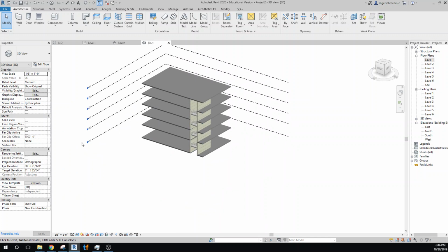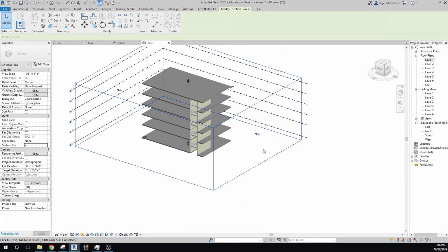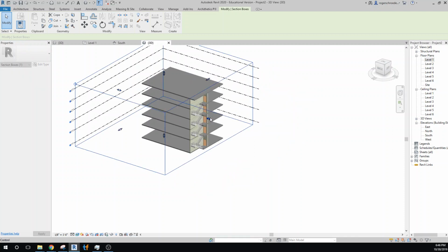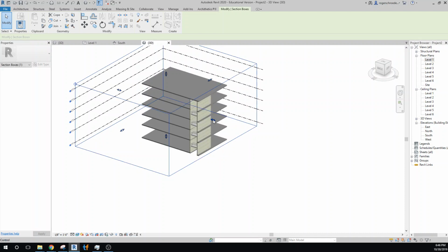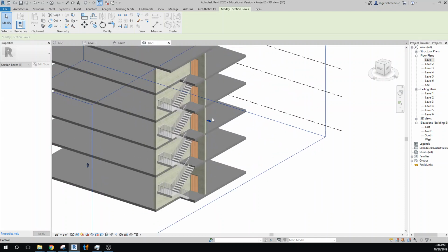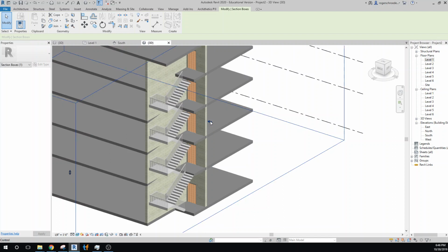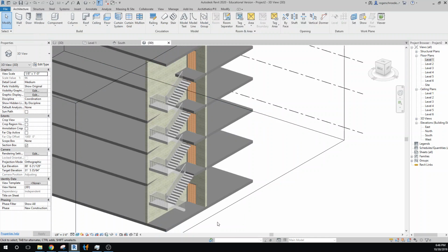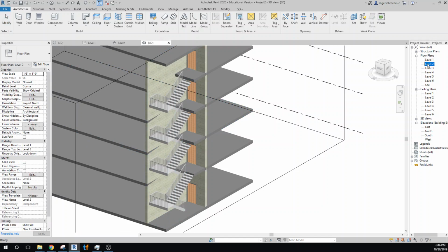And we'll think about ways of actually presenting this that make it a little more descriptive. Maybe pulling back a section box until we can show the whole construction of the stairwell. Need to zoom in there a little closer until we can get it just at the right position there. So, and we actually don't need the shaft wall going all the way down to the bottom. So you notice I can just pick this up again, and we've removed that shaft wall from that. And the other thing I'm a little bit unhappy about is the way I created the shaft wall with this floor deck intersecting it. So why don't we see if we can correct that now.